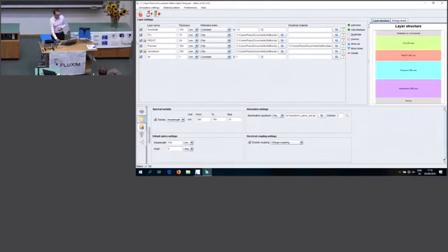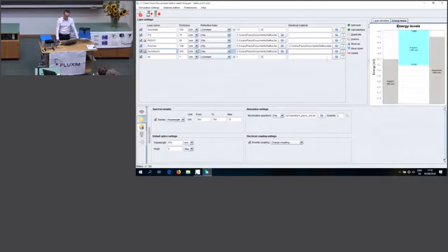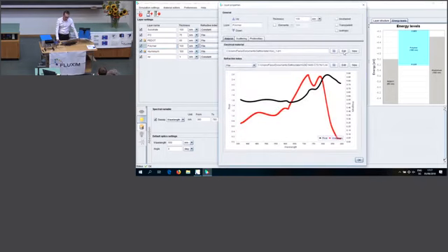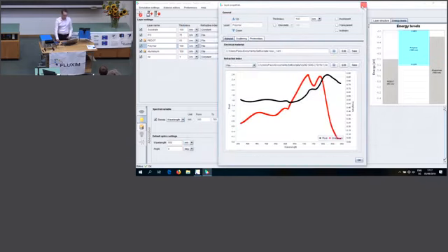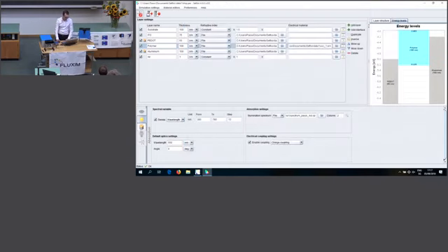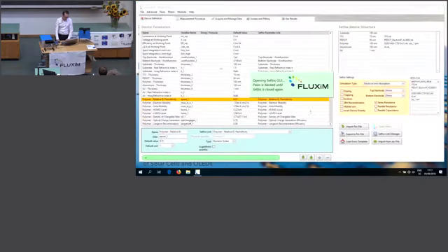So what you can do here, you define your layers. For example, here you see you have an ITO layer, PEDOT, then the polymer in the middle, and some aluminium. And here you see a graphical display, and you see the energy diagram. And for example, here you can now go and define exactly what N and K values you want to use, or you can define the HOMO level, LUMO level, the different mobilities, and so on. So once you have done this, you can go back.